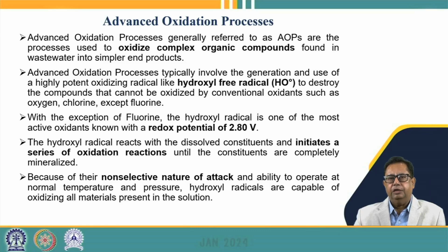So they can contain certain compounds which can be highly toxic to the bacteria which are used in the conventional treatment processes. So it is necessary that we oxidize these compounds so that they can be totally omitted from the wastewater and the wastewater can be further degraded by the conventional treatment process. For example, pharmaceutical wastewater may contain certain pharmaceutical compounds which can be toxic to the microbes.